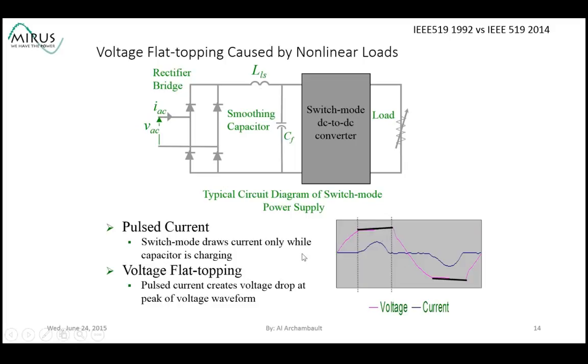And you can see the pulsing current here. And here's the voltage right at the pulsing device. So what's happened to this voltage is Ohm's law says that if we pass current through impedances, we're going to lose some of the voltage. So the result is the worst place for voltage distortion is at the device creating the pulsing current, and you can see that here.